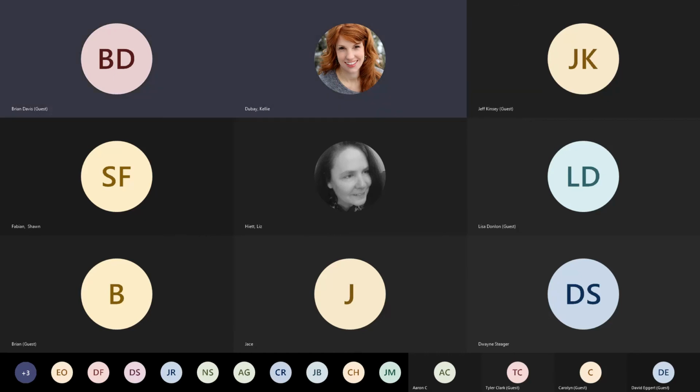Generally, I think the best way to do it is to prioritize it in groups. You look for larger groups. In our township, we have about, I think it's 87 outfalls. So if you want to do at least 2 inspections of those outfalls every 5 years, there's a certain amount that you need to do every year, like 30 to 40 or so. So you kind of want to group them into those manageable amounts that you can handle.